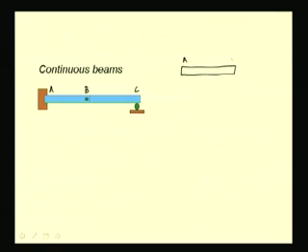So, first let us consider the beam AB, and at A, since it is fixed, we have the 2 components of reaction and the moment reaction, and at B, since it is pin connected, we have 2 joint forces, say By and Bx. Since the beam BC can rotate freely about this point B, there is no moment force at this joint.